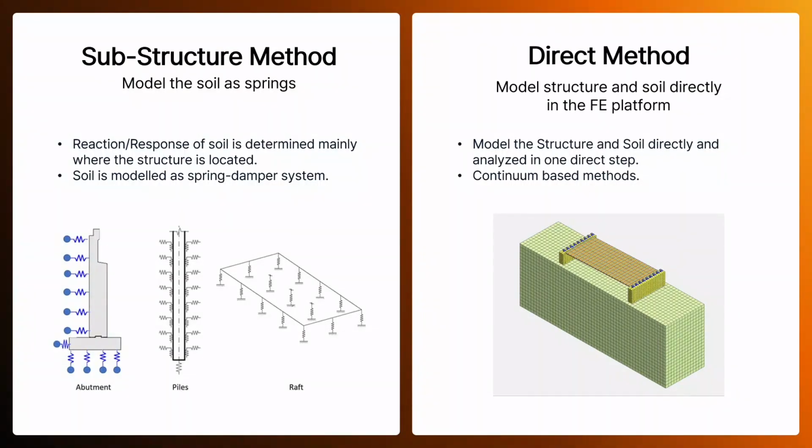For example, we have p-y curves, which give you the lateral deformations for lateral loads, and t-z curves, which provide the settlement for vertical loading. These are determined from certain criteria or constants, for example the modulus of subgrade reaction, that tells us how the soil behaves.